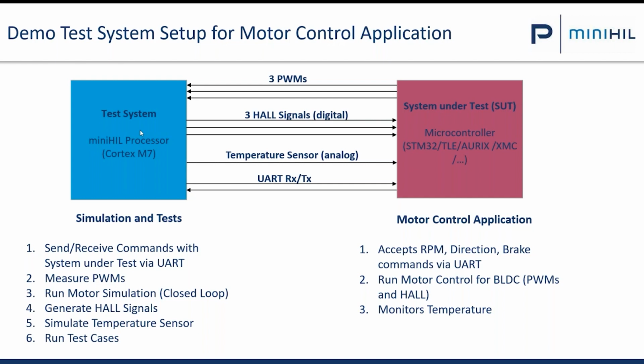And based on the simulated environment, I can bring my system under test into any state I want it to be. I can destroy signals. I can make failure injection by doing the wrong temperature or whatever I want. Since it's all simulated, except for the hardware signals, everything else is simulated, so I can do whatever I want with the system. And that enables a lot of different test cases.